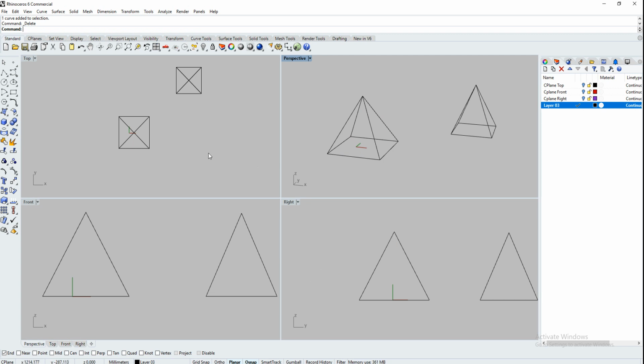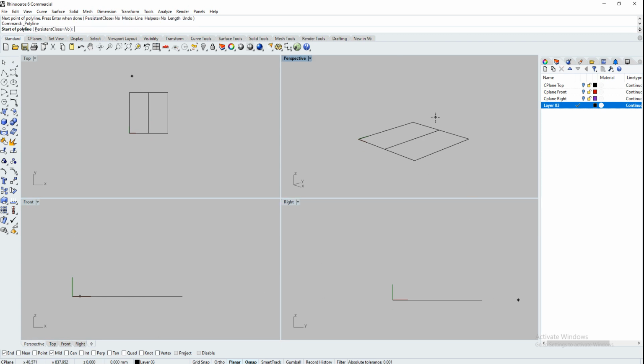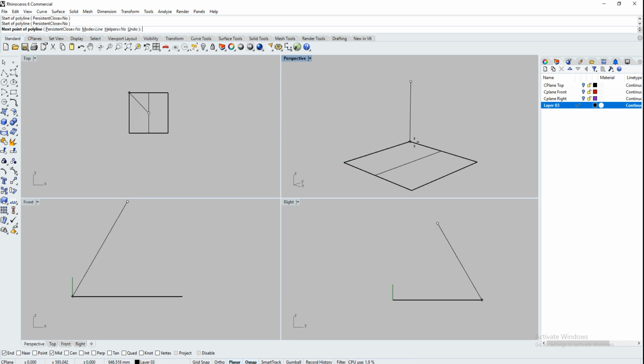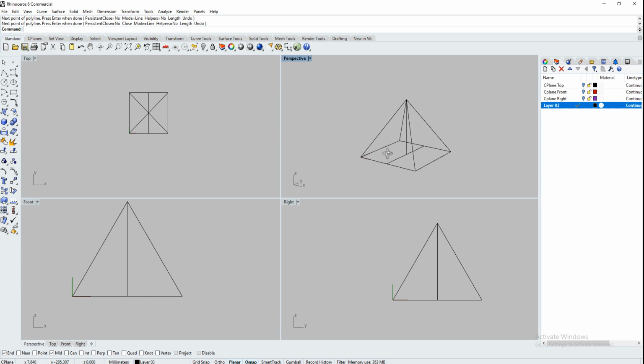This all can actually be done in the perspective viewport. Snap from the middle to the middle. And then remember, if you wanted to move perpendicular to the construction plane, you hold down the Control key, which I'm doing right now. That allows you to go perpendicular. So that's an example of how you can draw everything in the perspective viewport.